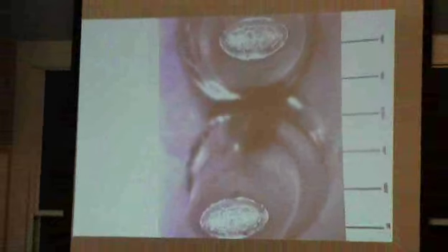This is the cup cone failure from another specimen, and it started out as a circle, and when it necked down, it's no longer a circle, it's an ellipse. There was texture in this piece of steel. How do I know? Because dE, it has an R value, it's not 1, right? dE2 over dE3, you know, E2 and E3 are different.